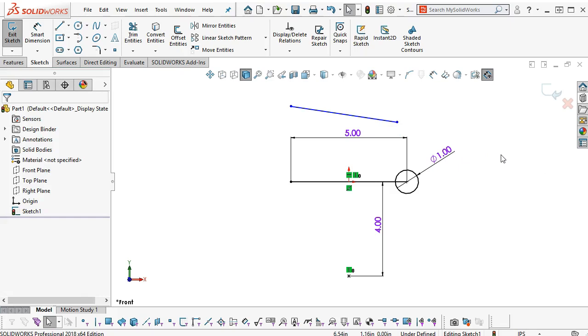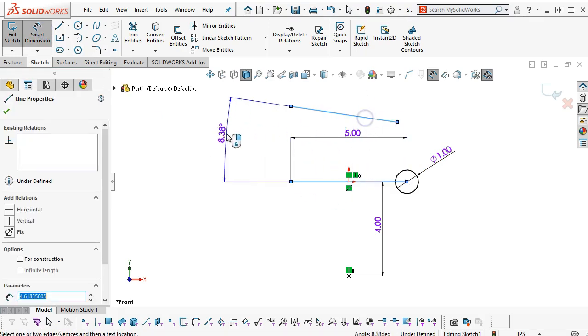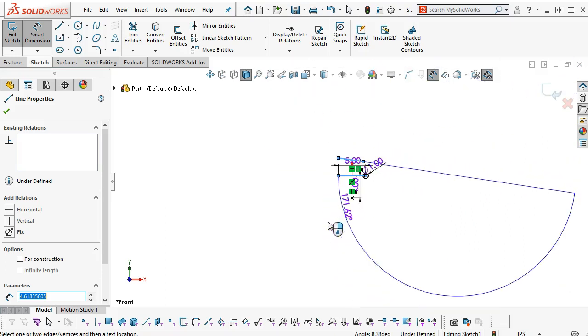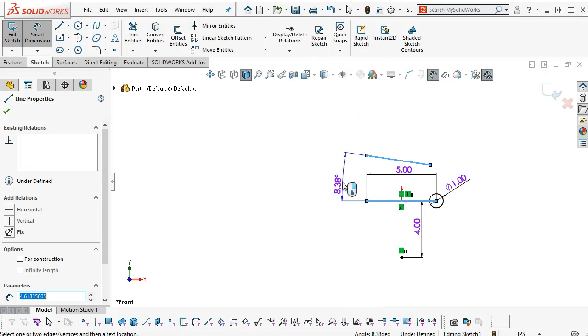and since what I generated is an angle, all right, it's not parallel to the line. Watch what happens when I apply this dimension. Okay, as soon as I go between those two objects, the two lines, now I'm in an angular dimension, and that angular dimension, depending on where I place the angle, is going to have several different solutions. They should all add up to 360 degrees, depending on coming off the horizontal, coming all the way around from the angle to whatever we need.